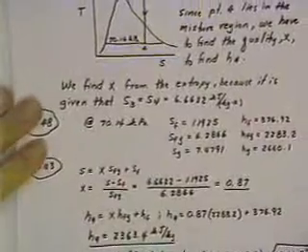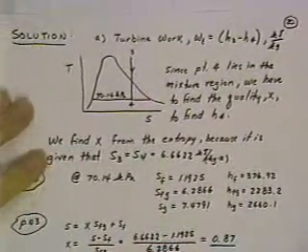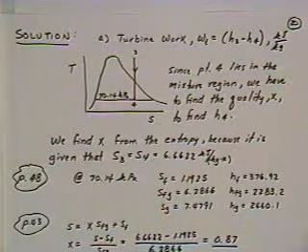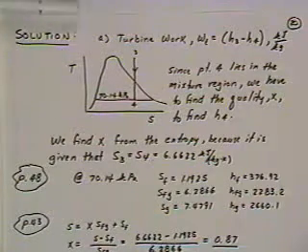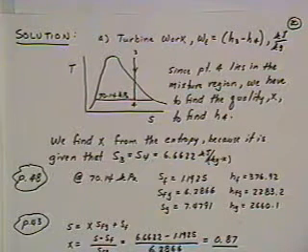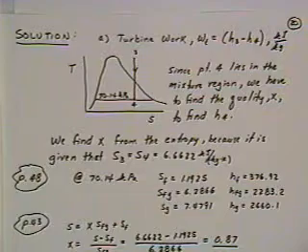Okay, so let's go through this on solutions, and we're going to assume that this is sort of one problem at a time, and we're going to go through and analyze each one of them in order to come up with the work. So, turbine work, the work of the turbine. This is again a device that we talked about. It's a device that has a control volume approach. Typically one inlet and one exit on these simple problems for simple power plants, and we ignore kinetic energy, we ignore potential energy, we ignore any heat losses, and everything's well insulated.